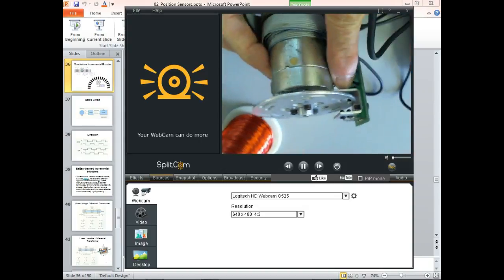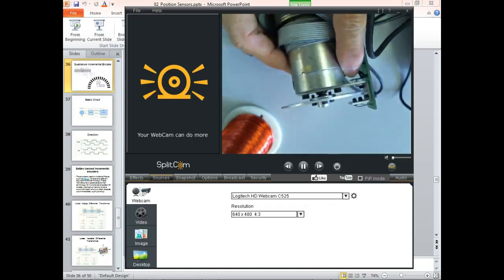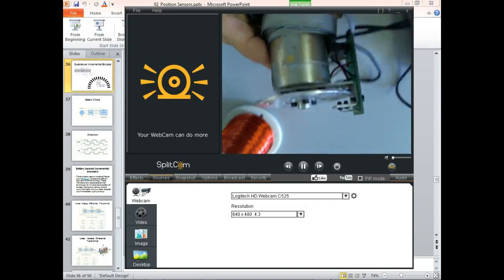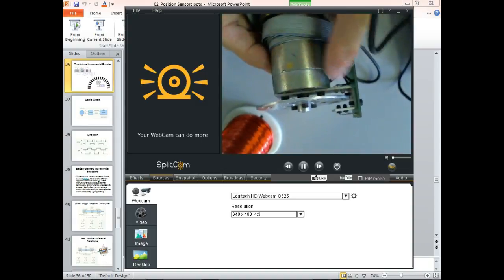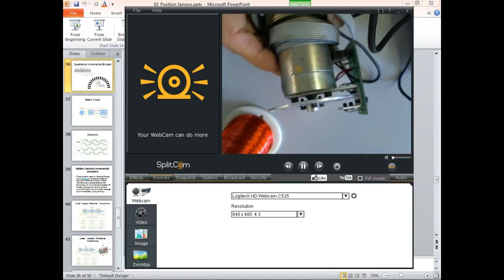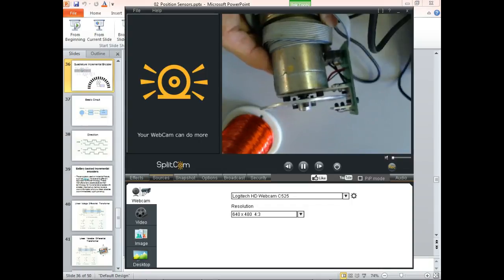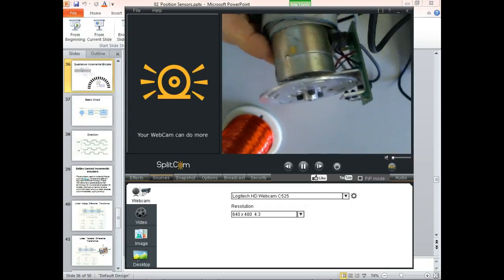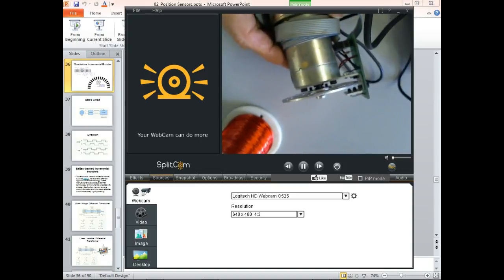So these are the photodiodes on this side, and they're the clear lens devices. They've only got two wires coming out of them, so I know they're photodiodes and not phototransistors. Phototransistors will have 3 leads coming out of them, but they look very similar. Y'all see what I'm talking about? Yes or no? Or y'all want to see it again?